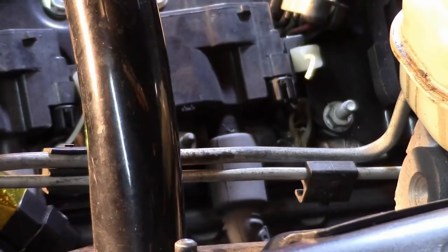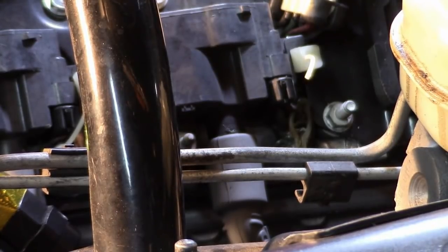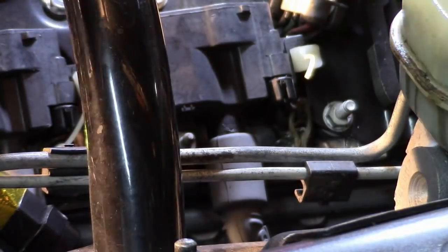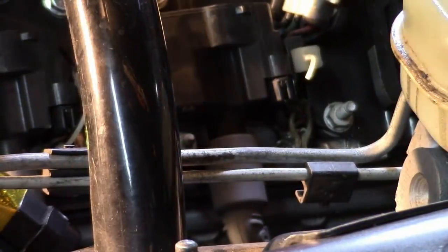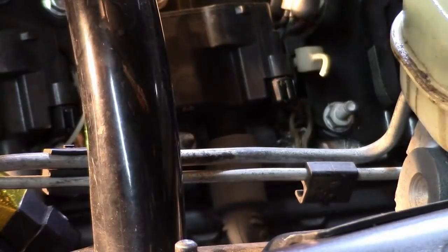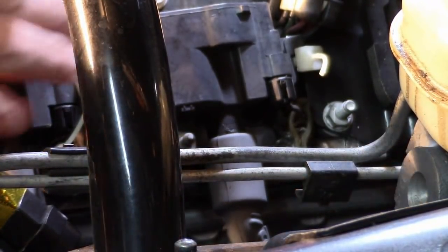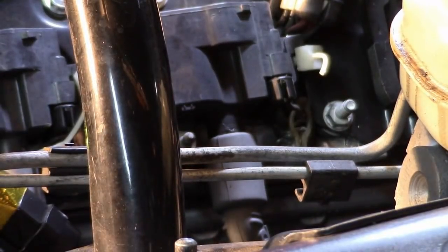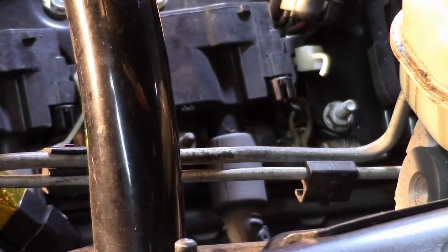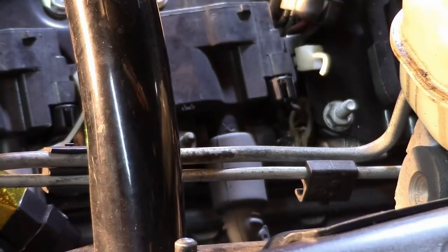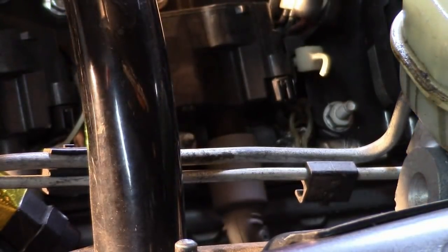They might even buy all the coils new because they don't want to replace them one at a time and keep replacing the intake manifold, right? People like us, however, are going to be able to access this connector, which will often be from outside of that intake manifold, and we'll be able to do our coil testing and ignition testing without removing the intake manifold. So that's another advantage when you understand these designs.